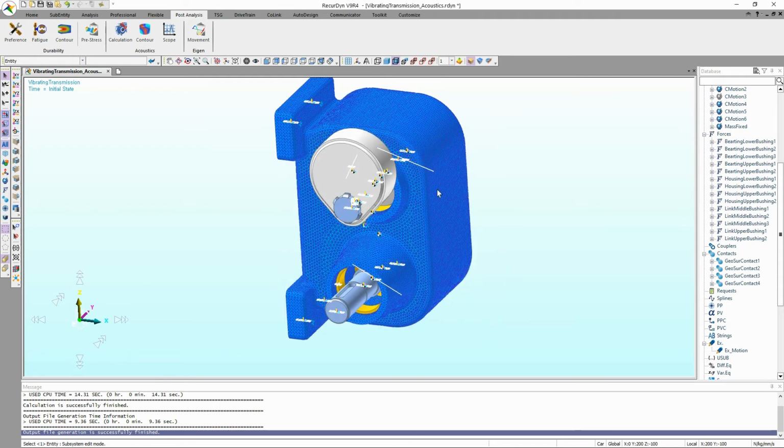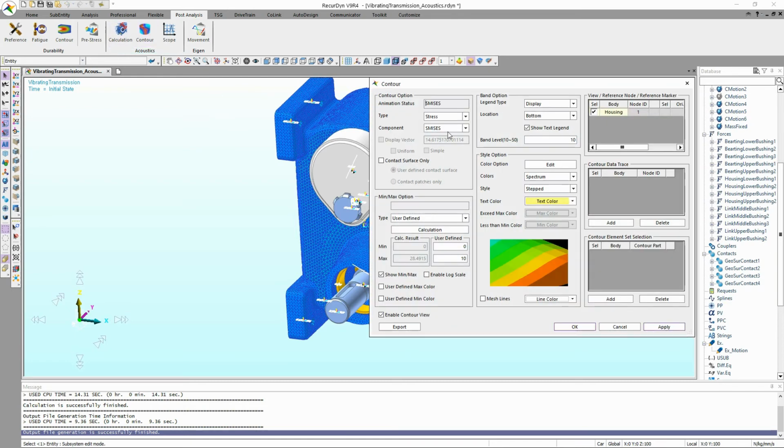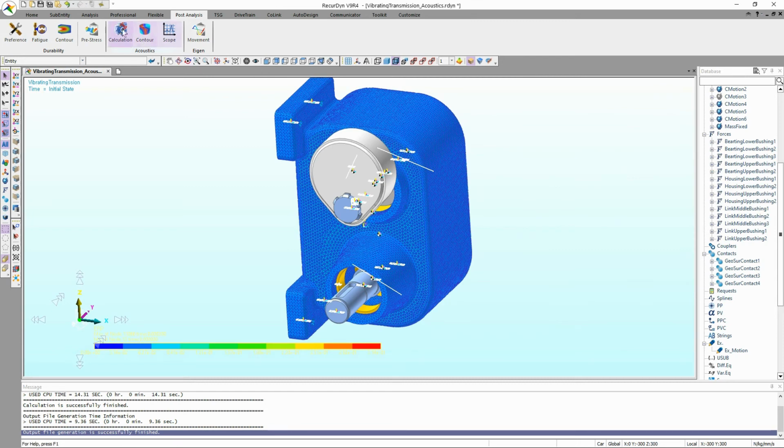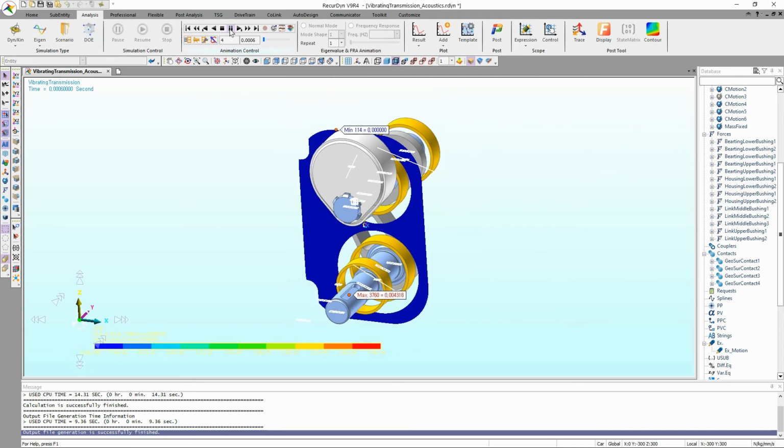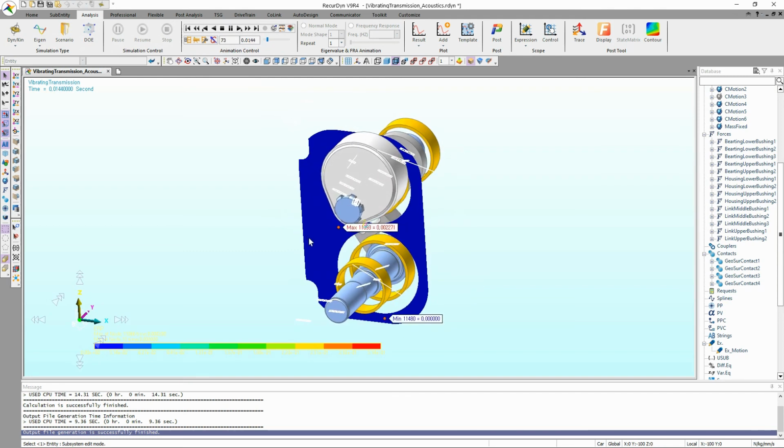After clicking the contour button, select Acoustics ERP type. You can check the ERP values for the specified patch set as contour plot. However, since the deviation of ERP values is very large, it is displayed only in blue.